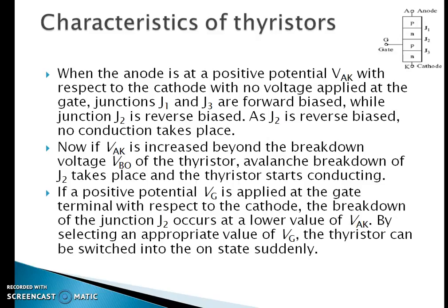But to trigger the SCR, we give a sufficient amount of anode to cathode voltage and apply the gate pulse, which may be a DC signal, AC signal or a pulse signal. Mostly in the laboratory, we use pulse triggering for the gate signal. The larger the gate current signal, the lower the requirement for the anode to cathode forward voltage.